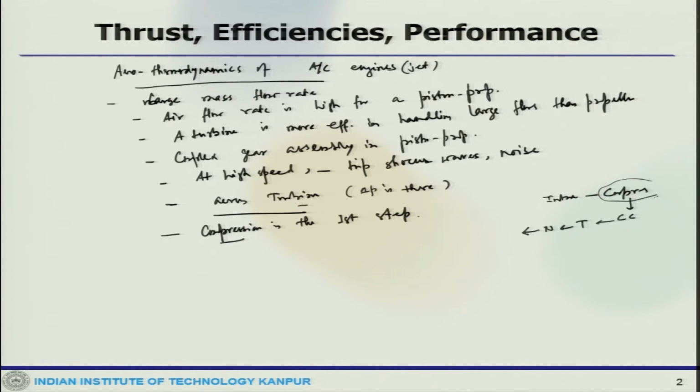So, in the ideal situation, one compressor and one ideal turbine, that means no loss, are coupled together, and then the combination can just turn itself, but you will get no useful work. The power developed by the turbine can be increased by adding energy to the working fluid.